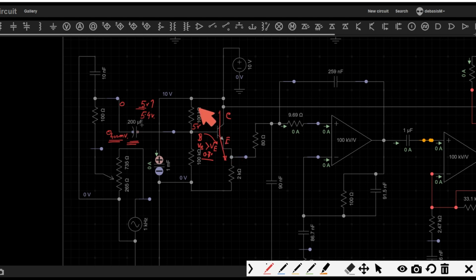Now one question comes: why is this signal detection required? Why can't we take this voltage directly to the downstream useful circuit? The problem is that the system requires some amount of current, or maybe the voltage requirement is high. The problem with the audio supply from the 3.5 pin is that if you draw a significantly higher amount of current from that pin, the audio card of your PC or mobile phone will create audio distortion. So this system is not designed to draw amps. It will not be able to give you a good amount of current even to operate the circuit. So for that you need a buffer zone.